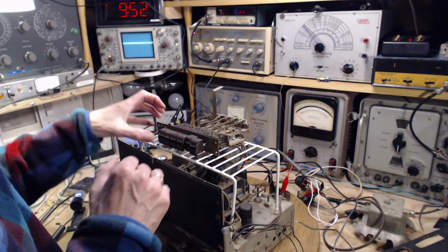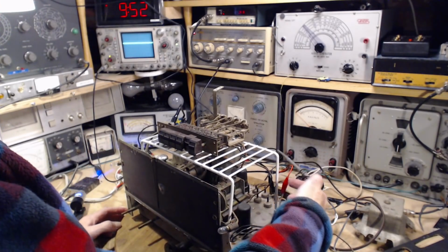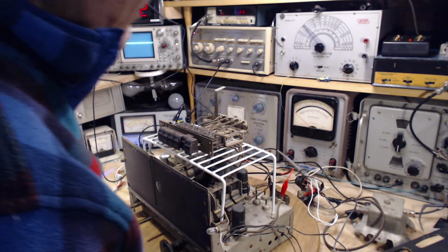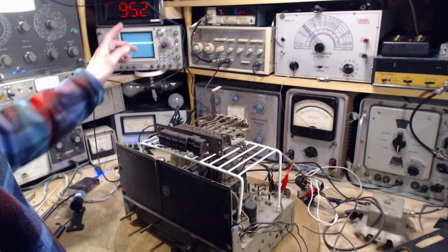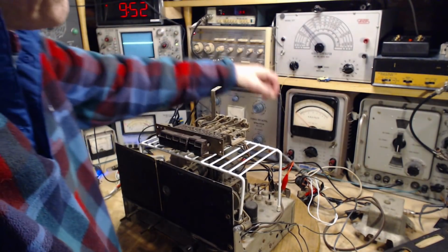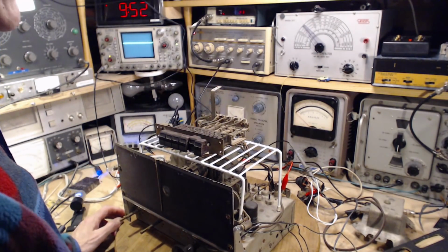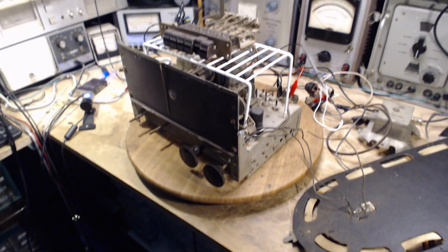Okay, we'll start by playing the radio first, so make sure it works the same as it did yesterday. I do have a connection to the antenna here that's coming from this signal generator, which I have not switched on, as I may not be interested in it. Play this audio, we'll listen to it come out of the speaker, we can look at it on the scope. The scope is hooked up right to the voice coil leads of the speaker. The speakers we're using, by the way, are mounted way up high. There's one of them, and the other one on the other side. Two in parallel to give us something close to the 3 ohms the radio is looking for.